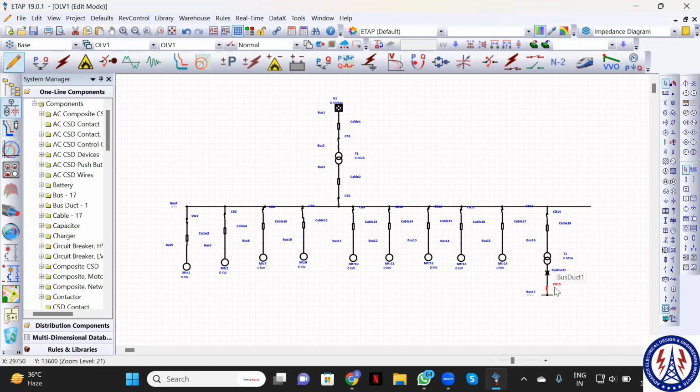What is the reason behind the bus duct, sir? See, basically, suppose you are taking the cable. In that cable, for the secondary side of the transformer, more number of runs will come, right? Means the cable runs will be higher. So it is difficult to terminate those high number of runs. So what we are doing, we will go for the bus duct and we will tell the switchgear vendor as well as the transformer vendor to make the flange like this.